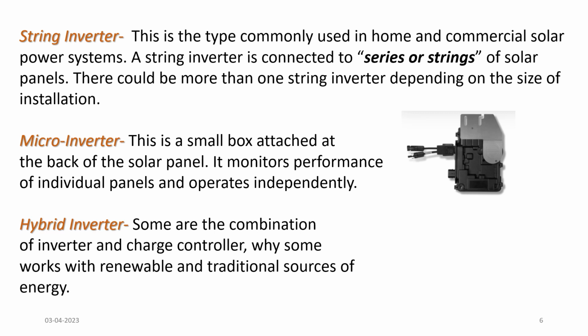The basic components of a solar inverter system installation are a PV panel, that's one, a charge controller, that's two, your inverter, and your battery. But some we call hybrid because you don't have to purchase another charge controller. They have an inbuilt charge controller. So some of them are regarded as hybrid.